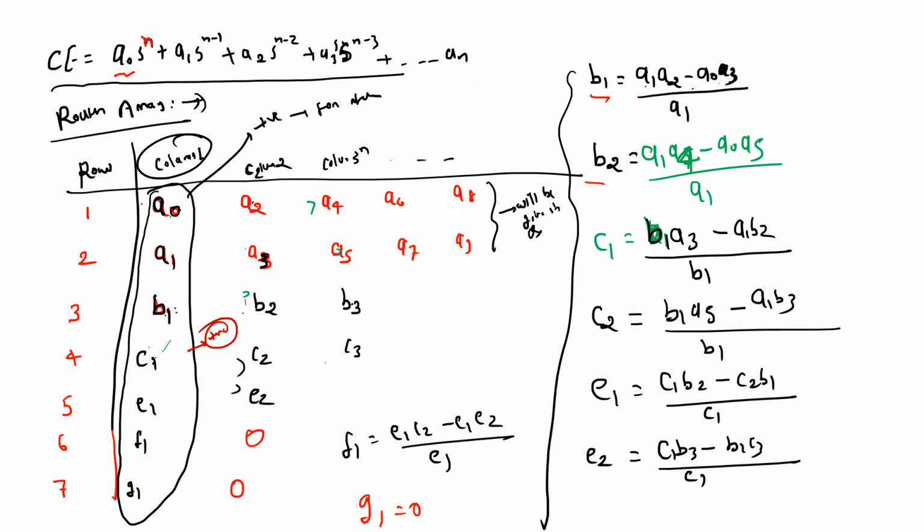The reason is that you only have to solve the closed loop transfer function and you'll get a polynomial in the s domain. While observing the coefficients of the characteristic equation, if all the coefficients are positive, then the system may be stable and may not be stable.